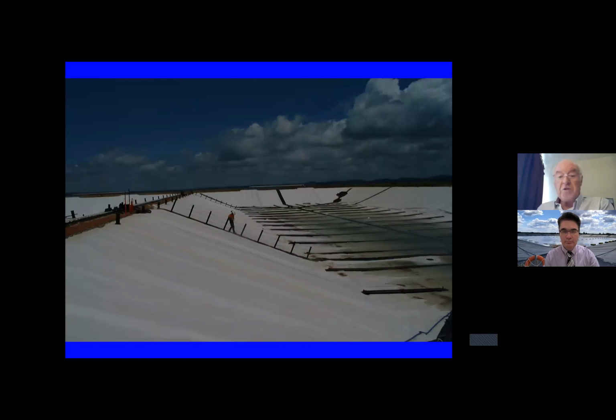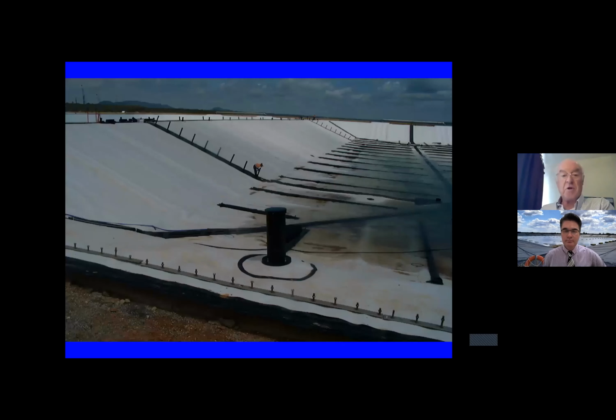Now that walkway is needed to get onto the cover for maintenance, to clear vegetation, and also we had two hatches in the cover to get to, to take samples of the sodium hydroxide, but also because we put samples of the geomembranes, we suspended them in the sodium hydroxide for future testing. And that's another picture of the cover, and in the foreground you can see one of the vents.